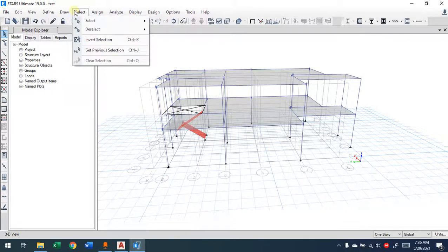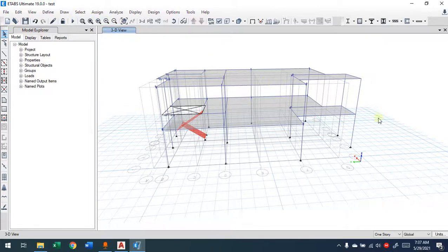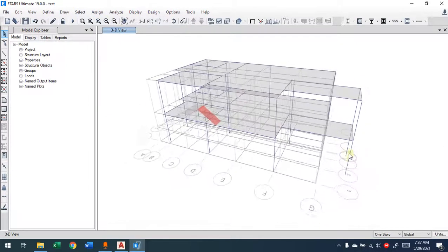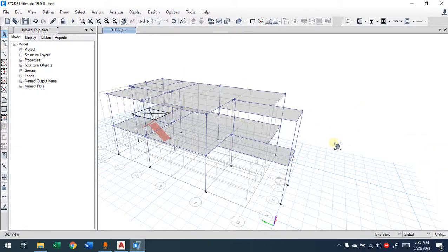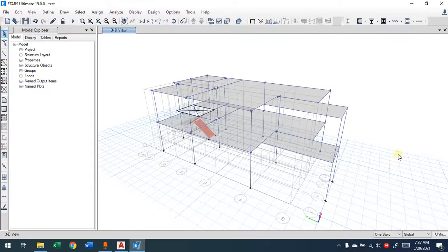Now, after this, let's say we did the modeling. So far, we're just modeling the objects, the elements that we have, to create the building as it is. So we're only focusing on columns, beams, slabs, and their connections. Here we're not drawing normal walls or windows. Those will not be considered in a design for ETABS. Those will just be considered as a load added to the frame.